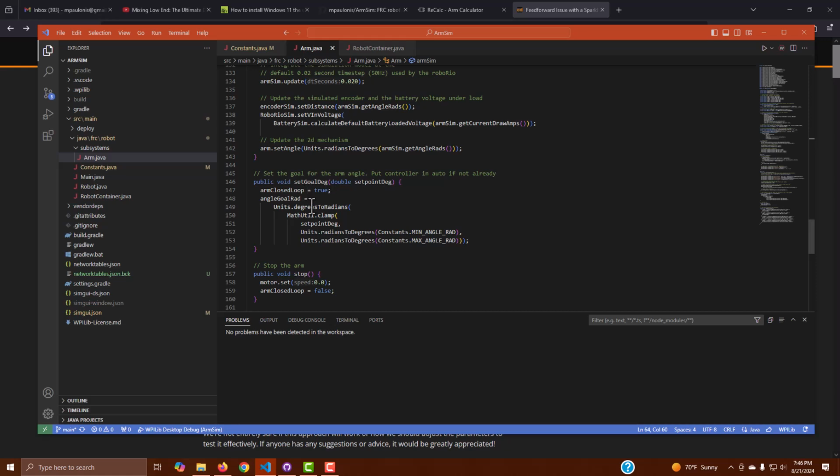And then the actual set point from the profiled PID controller follows the profile, and so it changes more slowly. It doesn't go immediately to goal. It moves over its trapezoidal velocity and acceleration limit path to get from where it is to the goal eventually. So goal is a specific thing, different really from set point in a profiled sense.